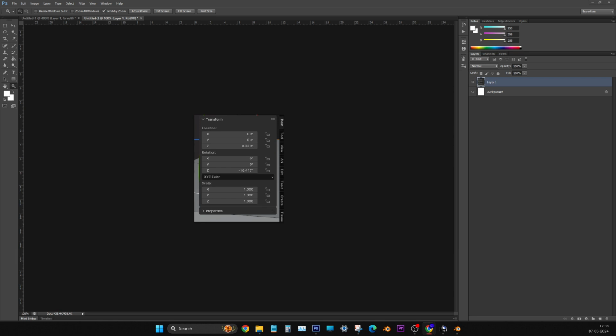Now we have to select there. You draw a small rectangle, only around that vertex. You take your cursor to the white color selected vertex. Yeah, there only you have to draw. But before that, you switch off this move handle, because otherwise it will be a hindrance. Press W. Now you draw the small rectangle around it. Yeah, that's all. Very good.